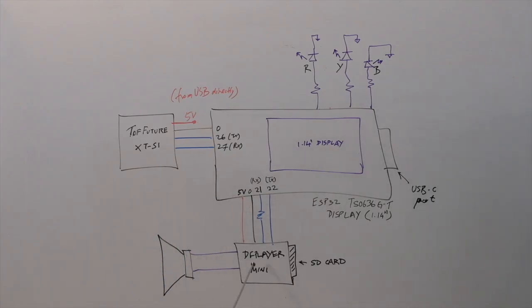And there's the DF Player Mini, which does the voice part of it. You need to have an SD card which has all the voice commands, like 50 feet, 40 feet, whatever information you want to give. It has to be properly recorded in MP3 format and put into this SD card, and then used to trigger the correct annunciation given whatever computation is going on as far as the height is concerned.